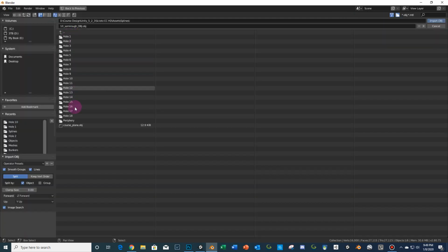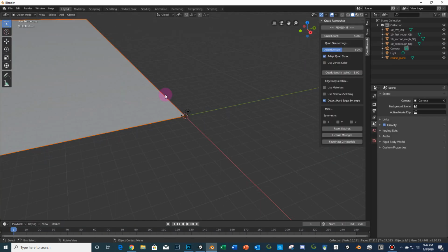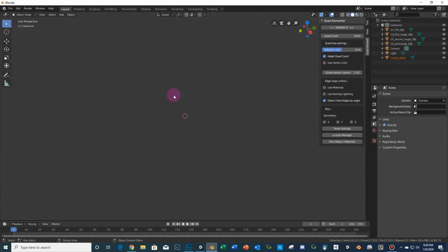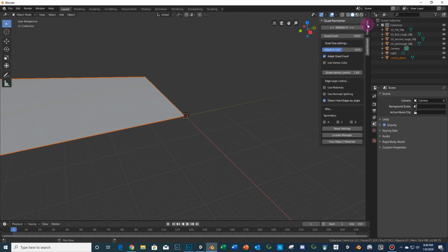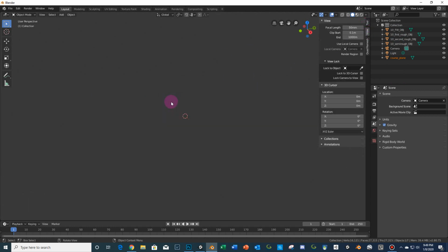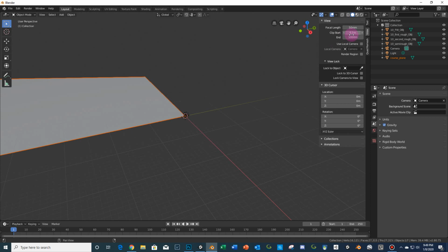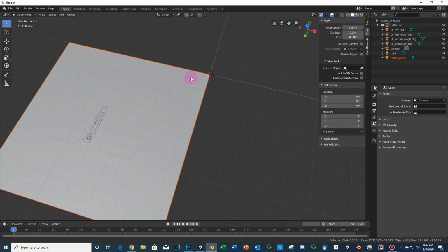Now, when I was doing this for the entire course, I actually did one hole at a time, but keep bringing them all in and have all these layers here, and it works out okay. In the view, when you zoom out, you'll see it disappears. We've got to fix where it clips here, but basically on the end of your clip, change this to 4,000. That should cover most people's terrain, but you could make it bigger if you need to.